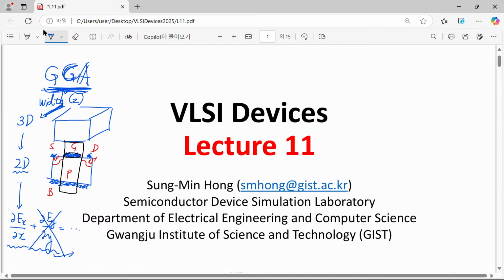Now we can do it in this way. Then if we neglect this term, what we have is epsilon over rho, silicon permittivity and rho, and this rho can have three different components: electron density, hole density and doping density. We believe that the doping is uniform and can be treated quite easily, but the other two are really position dependent.